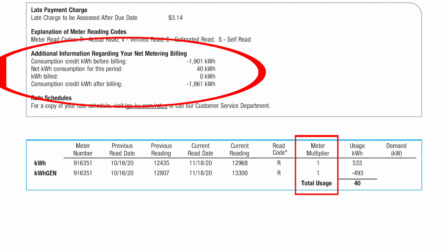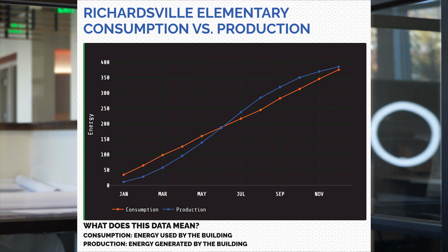And that's super important when looking at net zero or zero energy buildings, because the engineer should size that PV system appropriately. The engineer should look at how much that building is using on an annual basis from an energy point of view, and they should size a PV system to produce that amount of energy on an annual basis. So if we offset 100% of what the building is using through the PV, we've got a zero energy building.